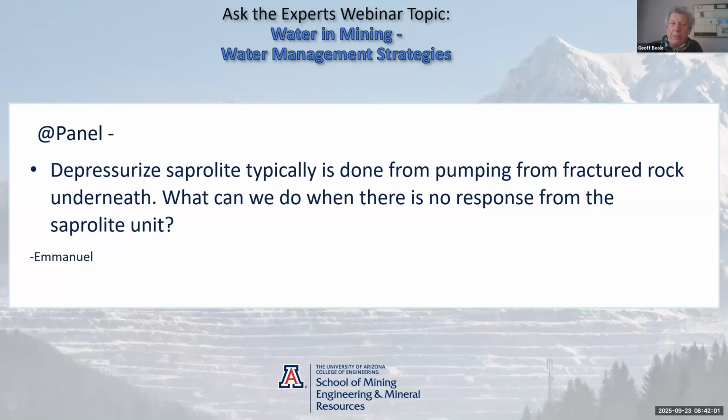The drains will typically need to be very shallow to the slope. Again, that is illustrated in the text that I referenced earlier, the guidelines for open pit design in weak rocks. The one in the chat. Yeah. And then conversely, when the saprolite may be permeable, but for whatever reason the saprock underneath isn't, then you normally switch to horizontal drains in the saprock or in the oxide zone.